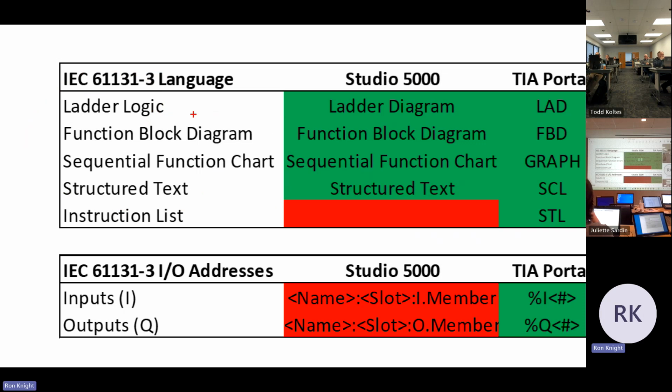So I've got customers that, they obviously know and love ladder logic. They begrudgingly let me do function block diagrams, mainly for PID loops, totalizers, discrete two-state devices, any kind of continuous flow stuff. FBDs are very good for that. I've got some process customers, not so much in Portal, but in PCS7, where we use SFCs a lot. Think a batching type process. I love structured text. I just don't get to use it very often.